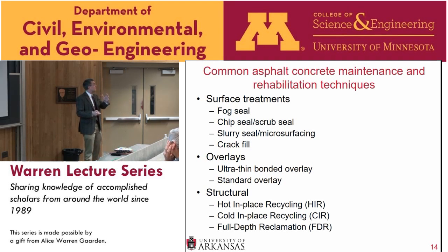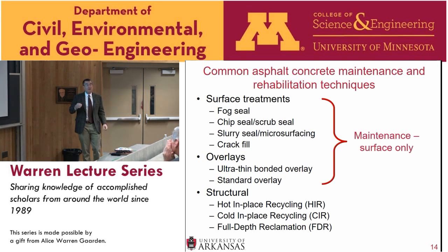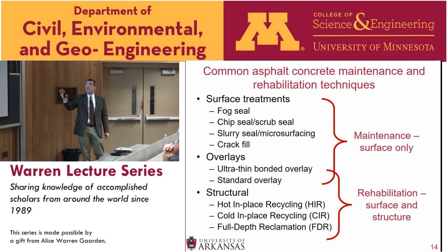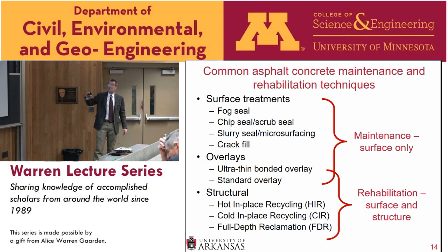And when we look at these options on a bigger scale, you can see here that the maintenance portion of pavement maintenance and rehabilitation, as I mentioned, it tends to deal with just that surface. And those are the surface treatments, and some people include the overlays. But when you talk about the rehabilitation, that's more of the structural, but then some people also include the overlays. So again, if you're at that conference with a bunch of pavement engineers, you can ask the question, is a standard overlay a maintenance or a rehabilitation technique? And people will be off to the races talking about whether it's one or the other. And there's a lot of discussion about that in our community. But in general, this is kind of how we split up the maintenance and rehabilitation activities. And there are more out there, but these are kind of the big ones. It's probably 95% of what's placed out on our roads right now.